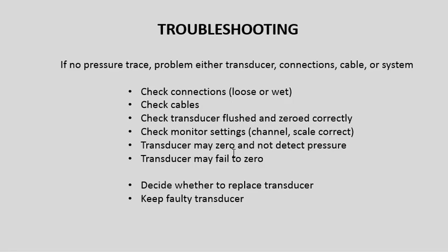The transducer may zero and not detect pressure, or the transducer may fail to zero. There are steps you can take to determine which. And you have to decide whether to replace the transducer, reboot the system, or some other approach, and always keep the faulty transducer for testing, just to confirm your diagnosis. That's enough on that topic.